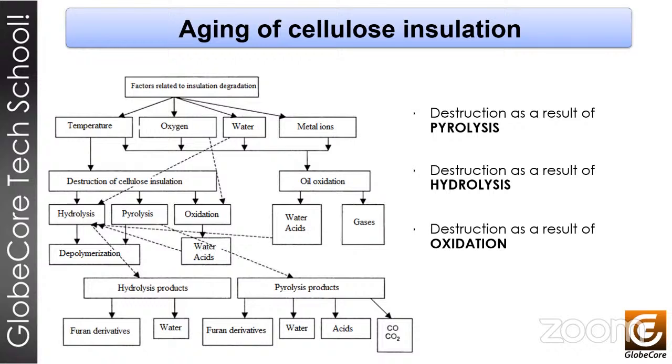Moisture present in oil is one of the most important factors affecting the insulation properties of paper insulation. The immediate cause of the decrease of the electrical strength of the oil is the presence of dissolved moisture in it. However, bound moisture easily turns into dissolved moisture. Therefore, it is considered appropriate to determine the total moisture in the oil. Moisture is associated with the breakdown strength of the oil through the oil-paper moisture exchange process. Measurement of relative oil moisture content in continuous monitoring systems is carried out using a thin film capacitive sensor.